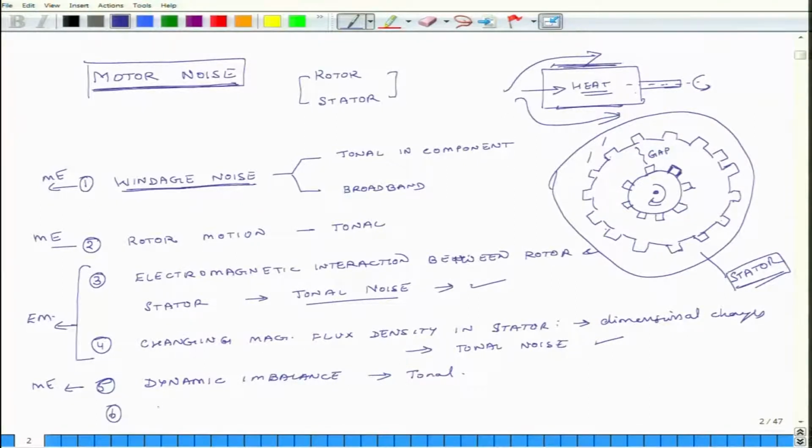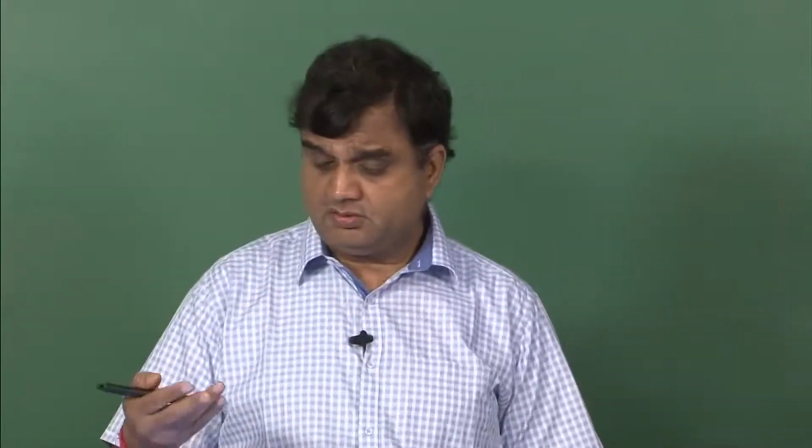and the last one is bearing noise. So, what is the deal about bearing noise? Because all these moving parts are resting in bearings, and when you rotate, the bearings also rotate, and in the bearings you have little balls, they are also rotating, and they have this type of noise. So, there is bearing noise. Okay. So, it is important to understand what different types of reasons are there which create generation of noise. Okay. The second thing we will like to understand is what types of motors are there.